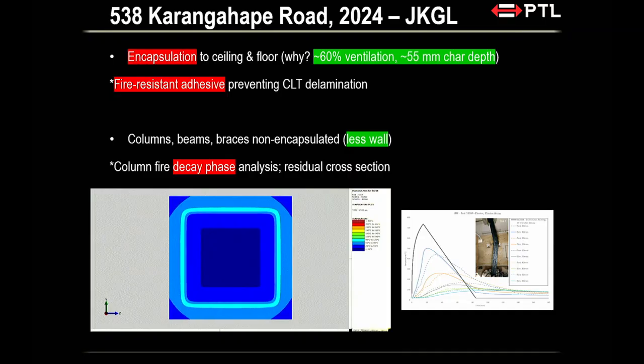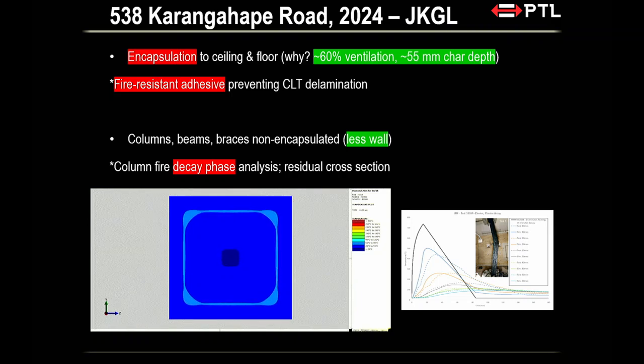So now the fire has decayed, right? So you can see the edges have cooled off, but just focus on the middle, 20 degrees Celsius. It continues to propagate, it continues to eat into your column, right? So if you think about where the 100 degrees Celsius is sitting, your column is continuing to shrink. So now, if you've done this analysis and you can figure out the maximum temperature reached along the fire until the fire has gone out for maybe another 2-3 hours, everything returned to ambient,